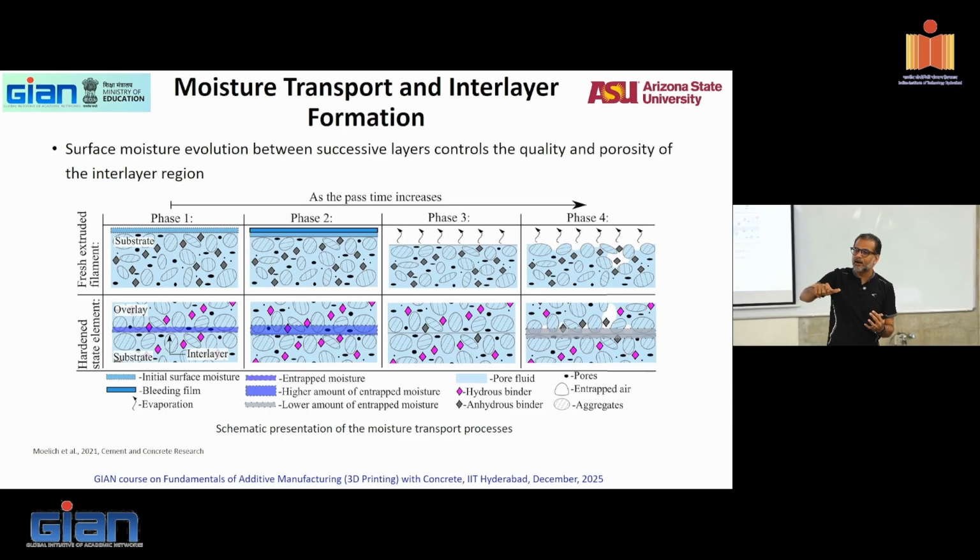And because on a curve, the material might tend to flow, you will have buckling and plastic collapse much faster. You'll have to think about all of that. While you do all of this and come back, you might have had a cold joint already. How do you account for that? So printing paths become an important idea in this.